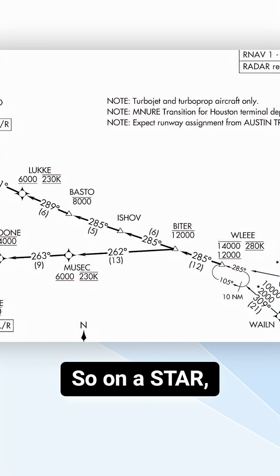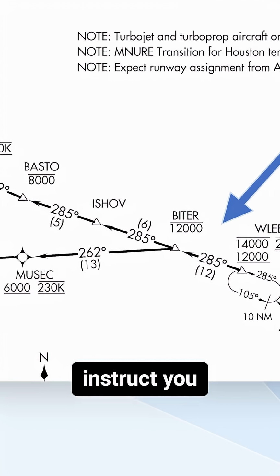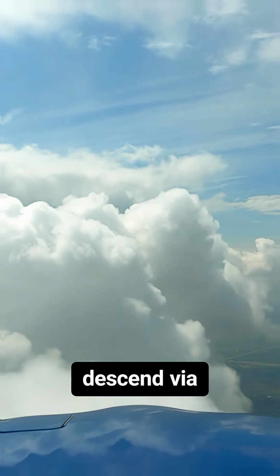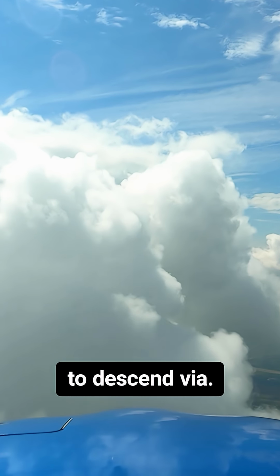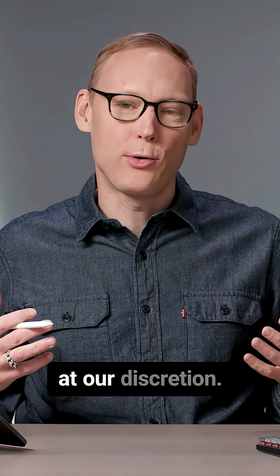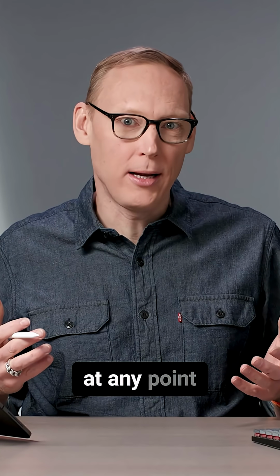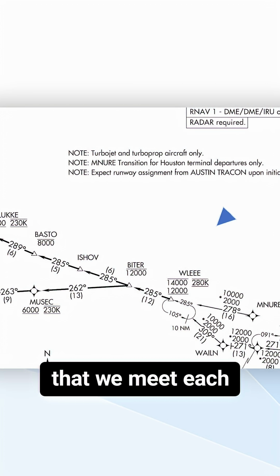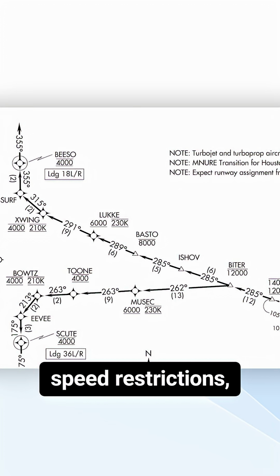So on a STAR, when ATC wants you to follow the altitude restrictions, they'll instruct you to descend via the STAR. Or you might hear descend via the arrival or descend via the Willie 7. But the key is you're told to descend via. When we're descending along an arrival, the descent is essentially at our discretion. We can choose our own rate. We can choose to level out at any point if we need to. We just need to make sure that we meet each one of the crossing restrictions and each one of the speed restrictions as well.